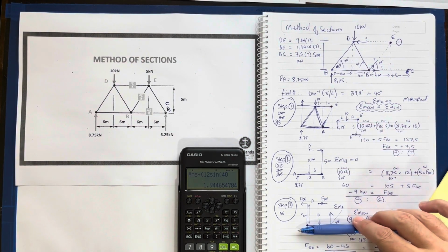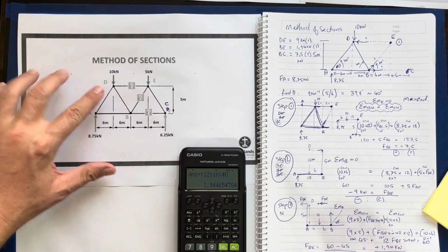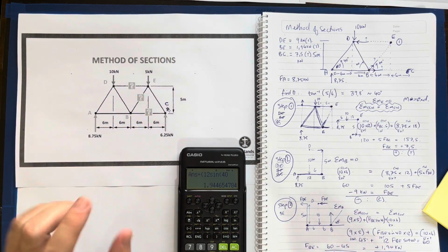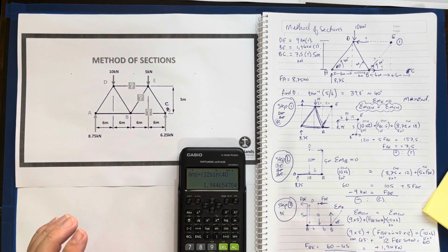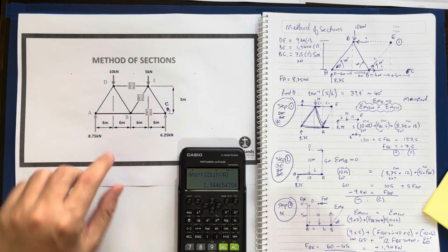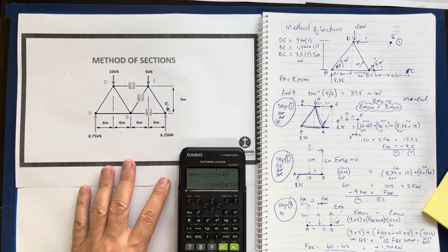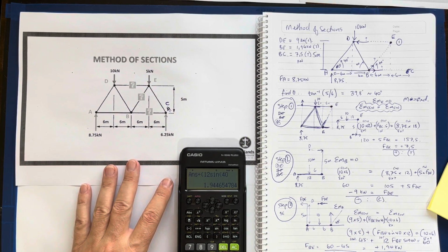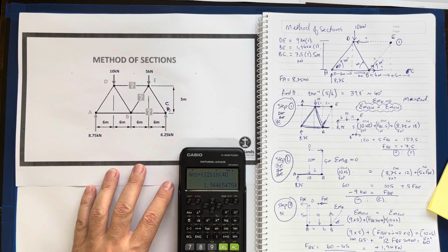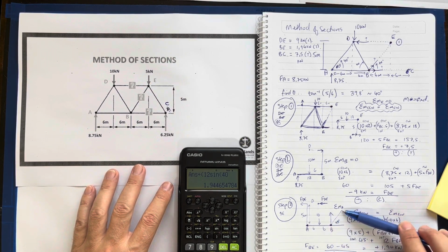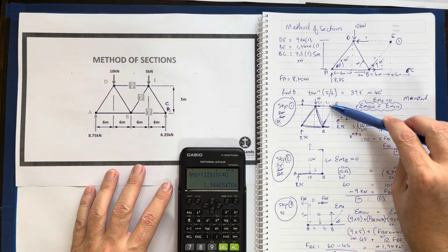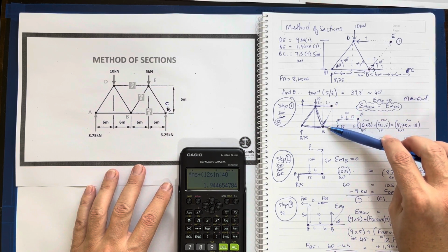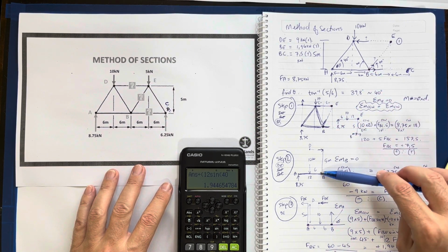Literally in 3 little steps, instead of having to solve every single force in every single member, I've just solved those, but instead of using sine, cos, and tan on my vertical and horizontal approach, I've just done it with moments, focusing on an area. So be cognizant of the fact that the process you follow, the last part is important, where if you're left with a diagonal, the first part, choose one where the two touch and you cancel them out and you find the other one.